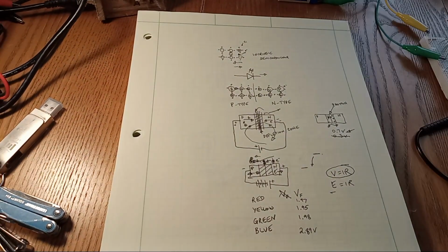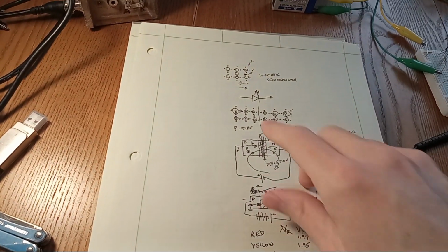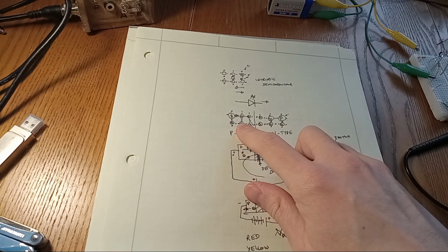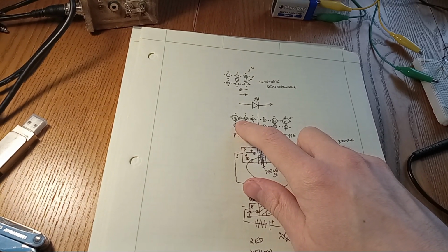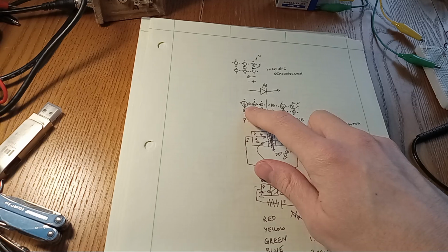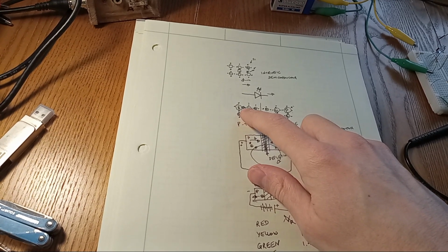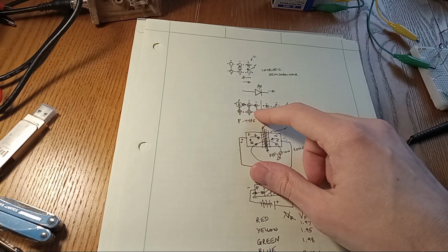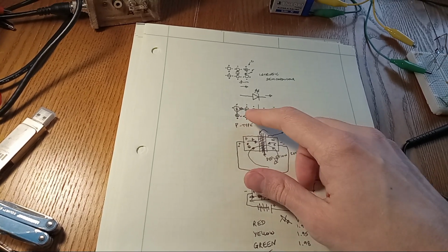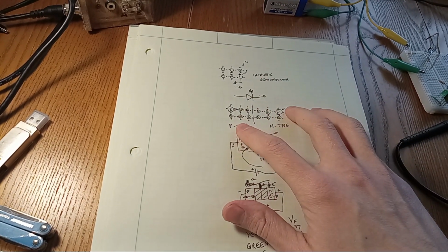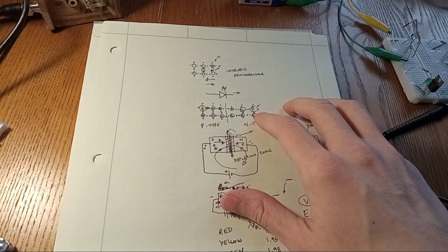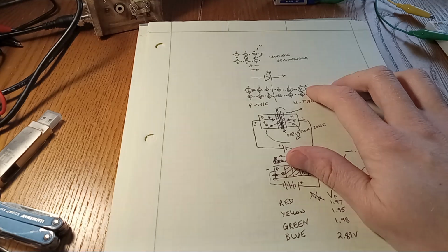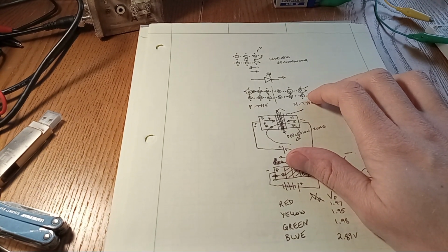for power transmission lines. Then we introduced semiconductors, talked about P and N-type semiconductors. P-type have atoms that have fewer than 4 valence electrons and create movable holes, which actually move about by the next electron filling in the hole and the next electron filling in that one, but it acts like a positive charge carrier. N-type semiconductor has an atom, such as phosphorus, that has more valence electrons than silicon's 4.